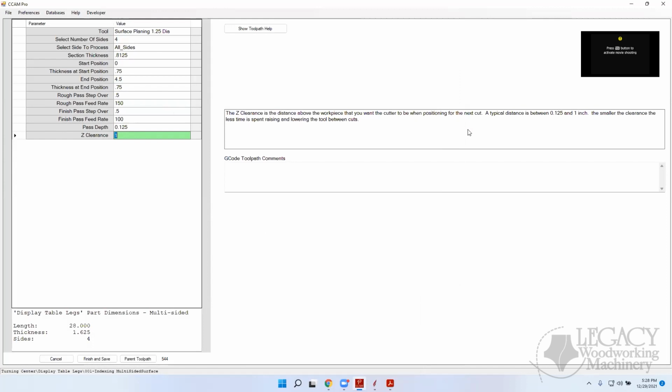that it's spinning. Yeah. When I'm turning around, it's only 1/8 of an inch, and you're going to put this value in. But when it's square, I don't want to catch that corner when it rotates. So in this particular case, I set it at 1 inch. And it's possible for us to take the square blank, and calculate the swing diameter and add 1/8 inch to that maybe. And so we could have a default value in there. That's something that we could add, which I think would be very powerful. It'd help out quite a bit because we wouldn't want to catch anybody by surprise.